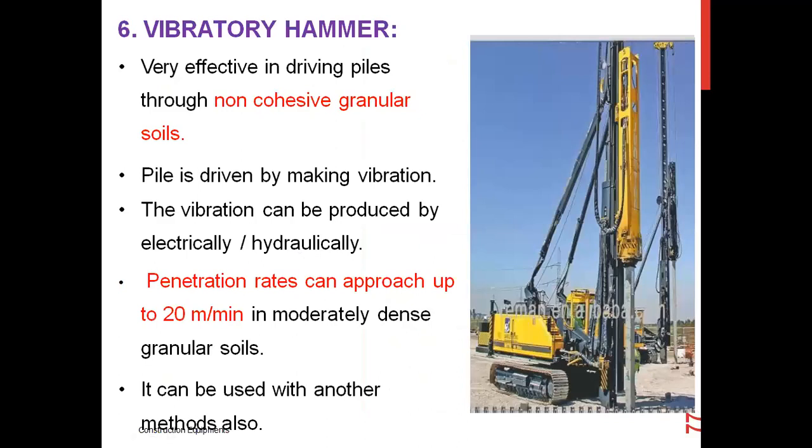Vibratory hammers are very effective in driving piles through non-cohesive granular soils. The pile is driven by making vibrations, which can be produced electrically or hydraulically.